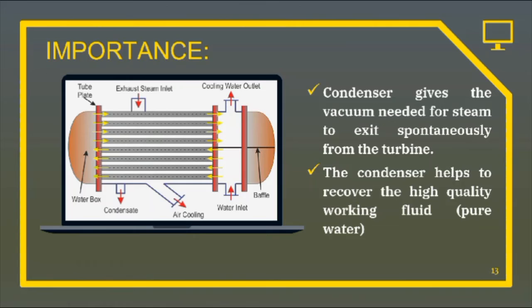Actually, purifying water is a tedious and energy-intensive process. We cannot afford to purify water throughout to compensate for exhaust steam. Thus, we prefer to have pure water locked in the cycle and recover it from steam for each and every cycle at the expense of the latent heat.